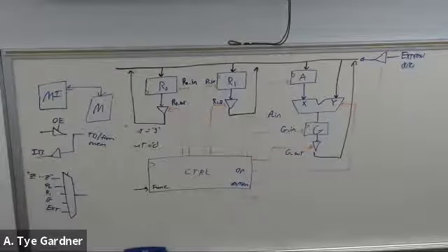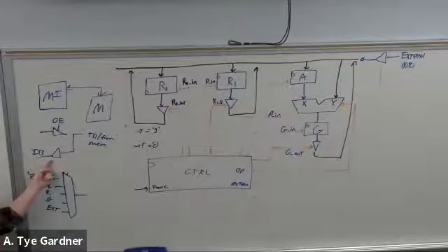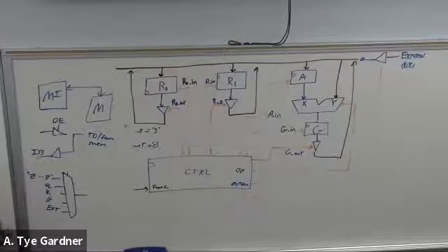Then we have to have something that tells the memory when it's okay to drive the internal bus, because maybe we want to do that inside of the microprocessor. Alternatively, you could create an output enable on that one, but in this case, we're going to do it on the memory side in project 3. Okay, does everyone understand this memory interface? Okay, good. That seemed to be a sticking point for some people.